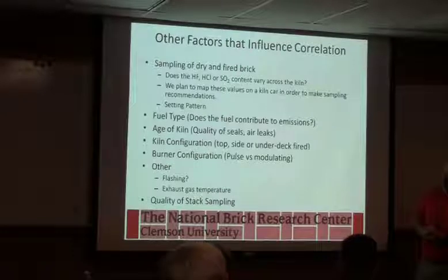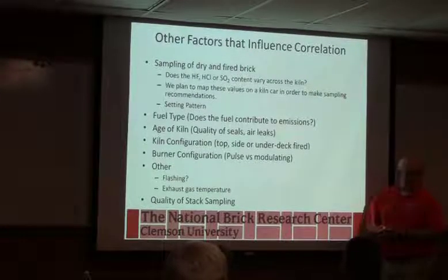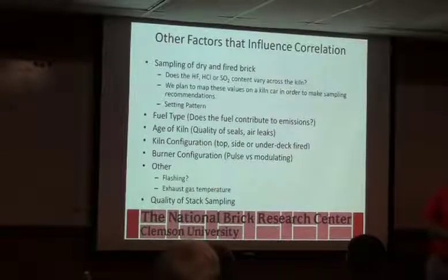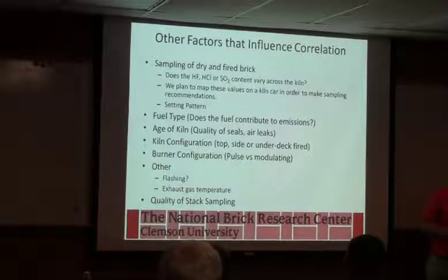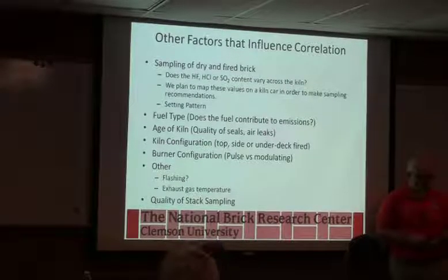And they've really been fighting that to try to get a fair rule from the EPA. Can plants meet that standard without a scrubber? It depends on your raw material, and it depends on your tonnage. So there are ways, and that's a whole other really complicated argument, but there's something called a synthetic minor. Basically, if you stay below a certain emission rate, usually by not processing more than a certain amount of material, you may be able to get away with no control.